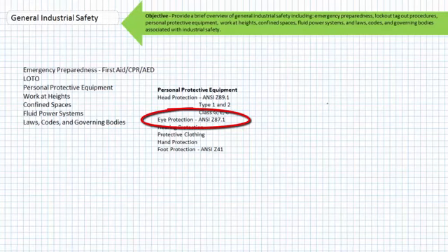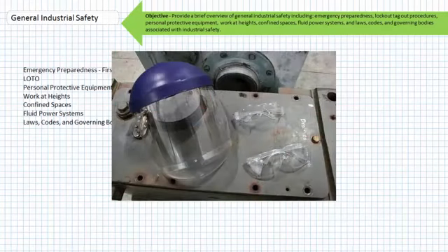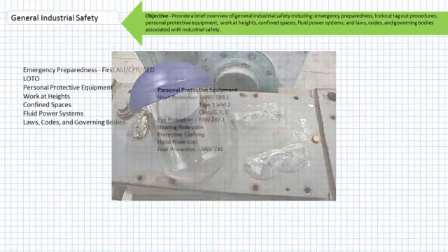Impact-resistant safety glasses with detachable or integrated side shields, goggles, or face shields are designed to protect the eyes from errant foreign objects. All eye protection is governed by ANSI Z87.1 and must state this on the frame. Goggles and larger safety glasses are designed to be worn over prescription glasses. Prescription glasses do not take the place of safety glasses and must be specially designed and approved by the ANSI Z87.1 standard if they are to perform this role.